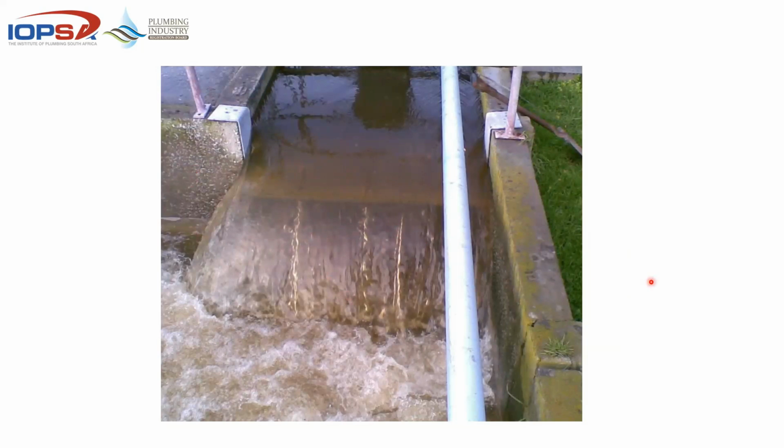So flooding is one thing, because it ends up going back into the area where it normally discharges. The issue normally comes in with those basins that you see next to the roadway as you pass your treatment works, those big round ponds. They all have little microbes in them, and little organisms that help with the digestion of the sewage. They help break down the solids into the silt at the bottom. But by flooding those things, you actually take all of those, let's call them the good organisms that we need. You actually flood them out.